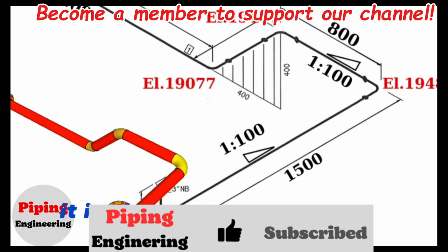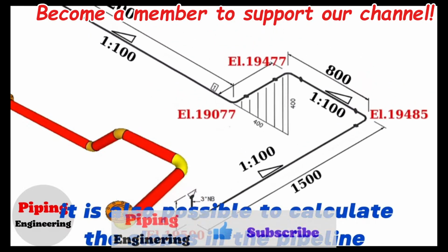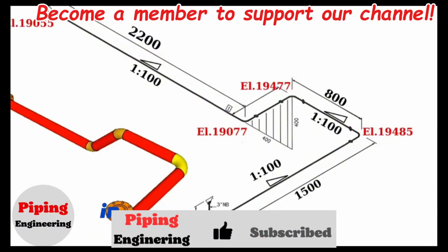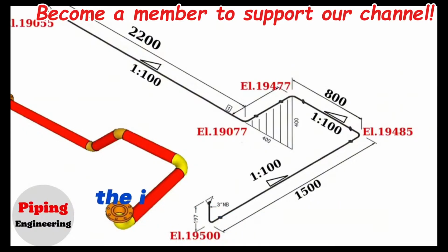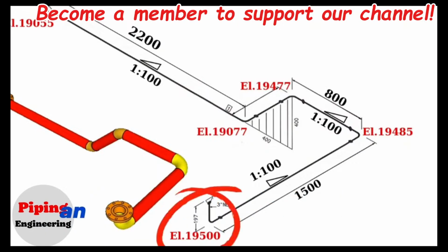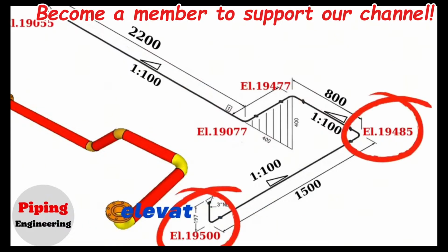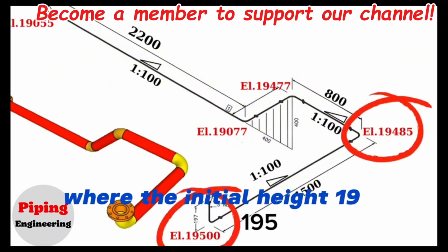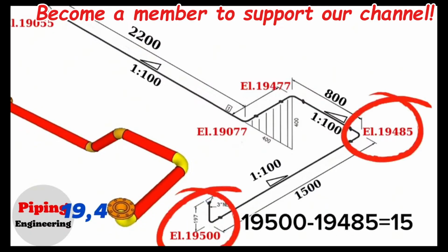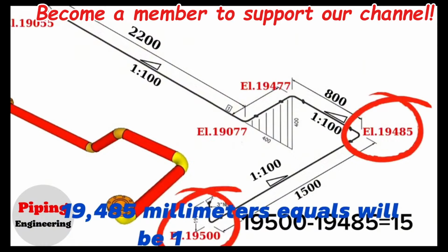It is also possible to calculate the slopes in the pipelines with the elevations shown at the turns in the pipeline. In this piping isometric drawing, the initial height of the pipeline elevation is 19,500 millimeters, and the height of the pipeline at the second turn with a slope of 1:100 is 19,485 millimeters. The initial height 19,500 millimeters minus the second height 19,485 millimeters equals 15 millimeters.